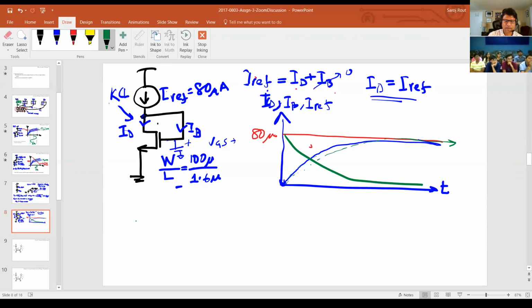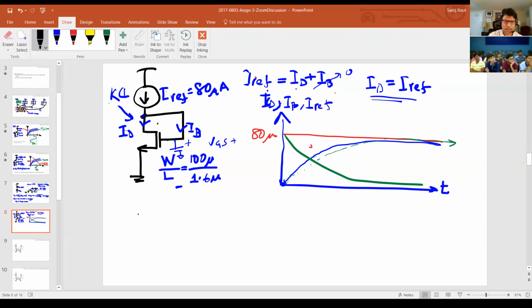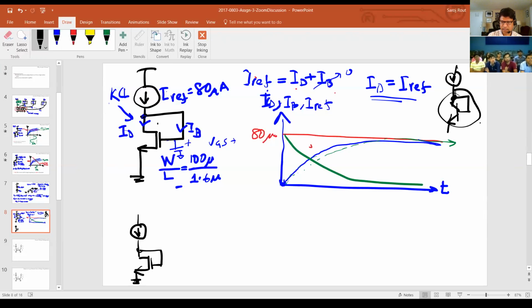So now you have the two recipes on how to make a current mirror, right? So you created this. You take this current and force it into this diode connected transistor. And the reason it's called a diode connected transistor is because of BJTs, or not, I shouldn't say BJTs, you still do that. You would do the same thing. You would connect it and put the current source here, but this is nothing but a diode, and that's why they're called diode connected transistors, right?